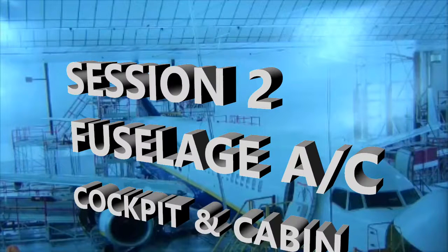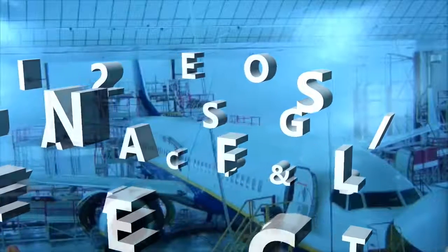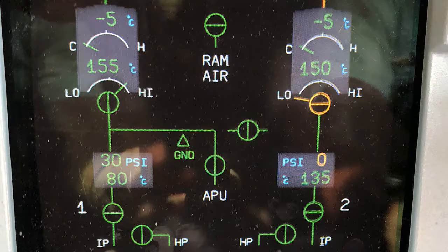The other thing you're going to have is the trim air system. The pack temperature control is only for the demand for the coldest air. The other two zones are controlled by the zone controller, and they receive additional heating from the trim air system. So the trim air system is a mix of the trim air and the mixed manifold air supply.